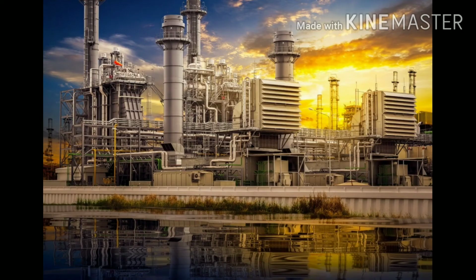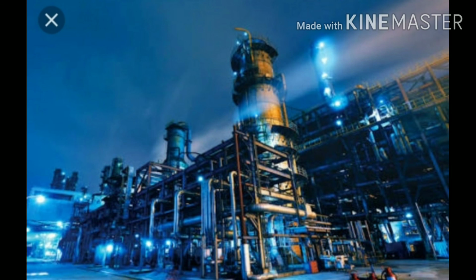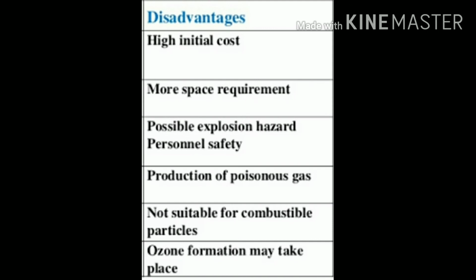Electrostatic precipitators are used in power generation industry, cement plant industry, paper mills, petrochemical industries and metallurgical industries. The advantages of electrostatic precipitators are: economical to operate, it provides high efficiency up to 99%, and it does not produce a moisture plume. Limitations are it does not work with moist flows, mist or sticky particles. It must be heated during startup and shut down to avoid corrosion from acid condensation. It is expensive to set up.